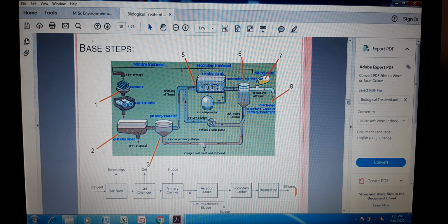That pump is again an aerator they have provided, meaning when it comes through this side, it is again provided the oxygen so that they do not die. So the oxygenation is continuously provided for their survival, and after this secondary clarifier it goes towards the tertiary treatment. Understood?